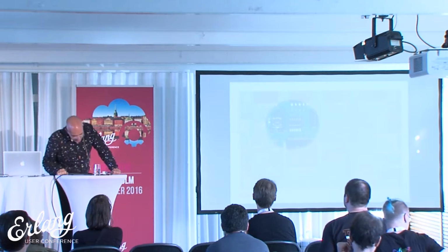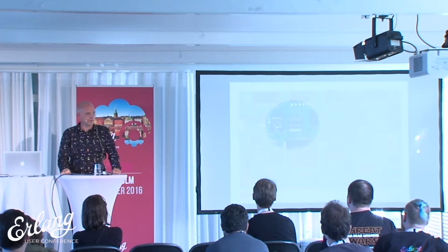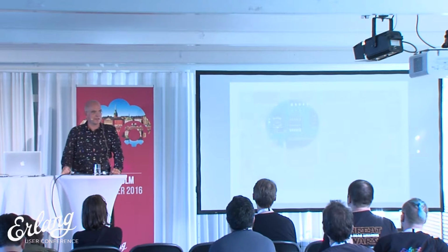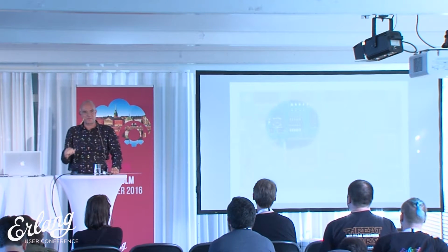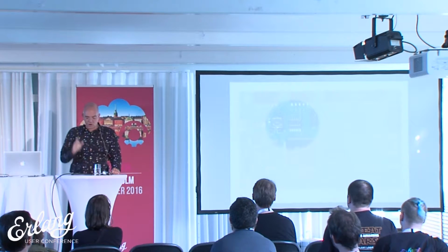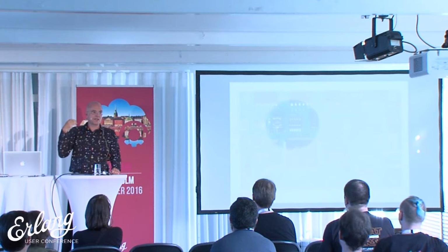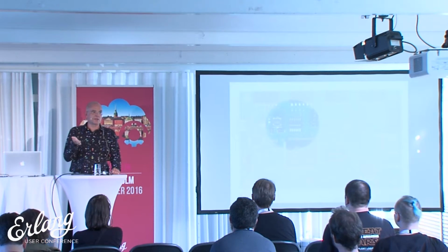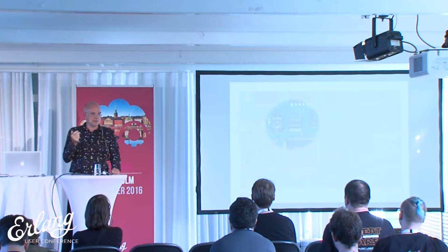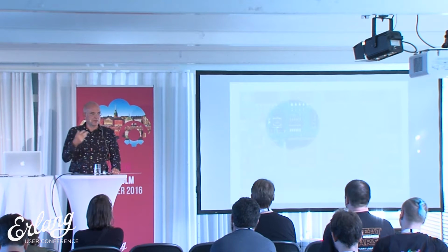So this is the user interface, the input. You have five little switches, which you can set to on and off. The sixth one is taken over for changing the debug thing. Oh, I forgot to say, on the USB interface, there's also the serial console, and there's also an onboard JTAG debugger. So you can do hardware level debugging with a very cheap adapter to access the onboard JTAG debugger. And then you can basically single step in the hardware.